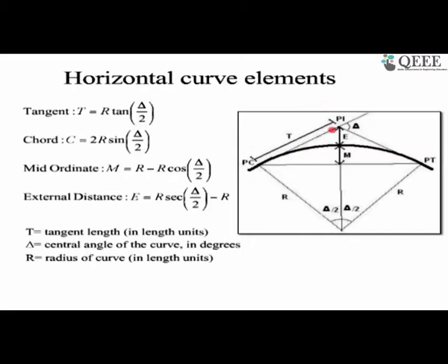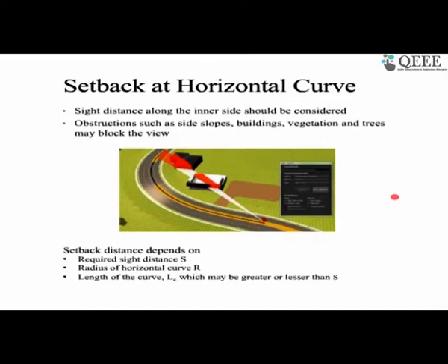Before I move on to the next one, I got another question. For a multi-lane two-way national highway like 4-lane or 6-lane, is it necessary to provide extra widening? Of course we do need to provide extra widening, because the mechanical widening is for each lane. You want to make sure that every lane is 100% utilized. You don't want half of the vehicle in one lane and the rear part in another lane because of this curve. So that is why you provide extra width there, so that the complete vehicle is in the same lane.